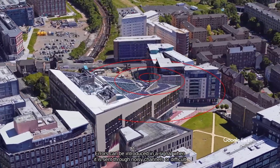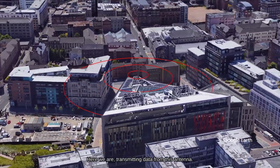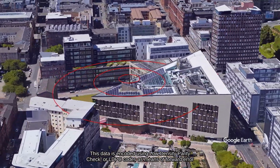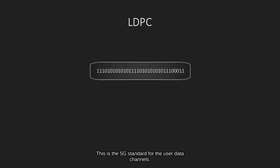Errors can be introduced in a signal when it is sent through noisy channels or difficult to navigate environments. Here we are transmitting data from this antenna. This data is encoded using low density parity check, or LDPC, codes as a means of forward error correction. This is the 5G standard for the user data channels.